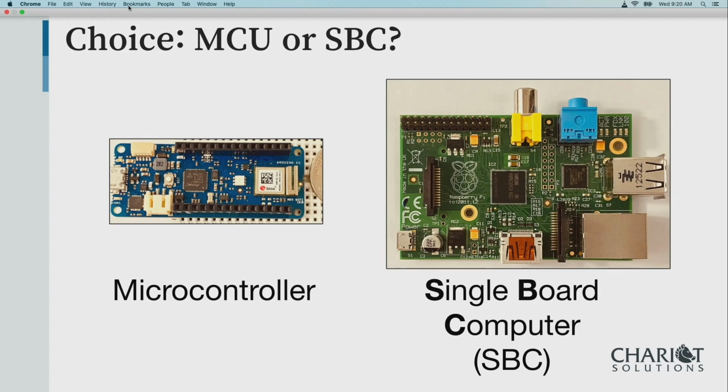So these are all things you can do with a microcontroller a lot easier than if you're running a Raspberry Pi and say, hey, let's shut down the operating system for an hour. Not so much. So they don't always have the low power on-off ability that a microcontroller does. Does this make sense in terms of the differences between the two? So that's why you would choose something like a single board computer with an actual operating system versus a microcontroller.